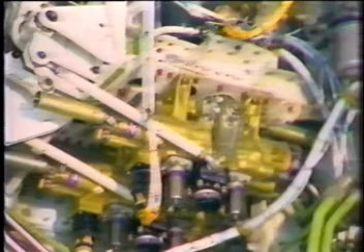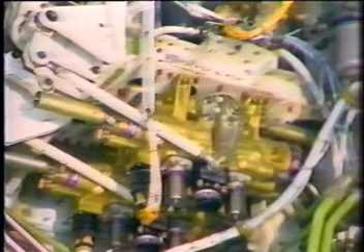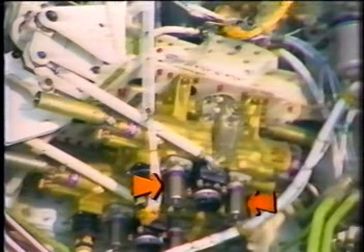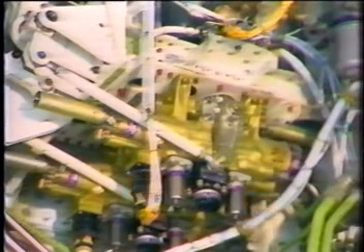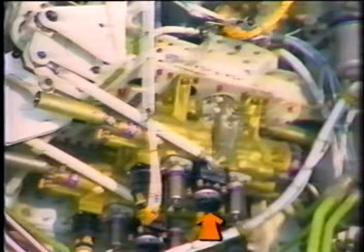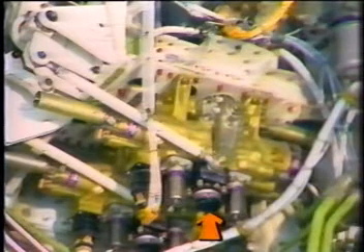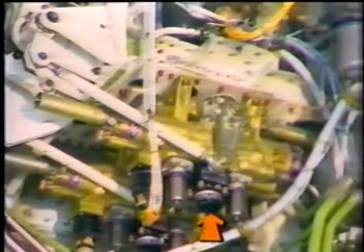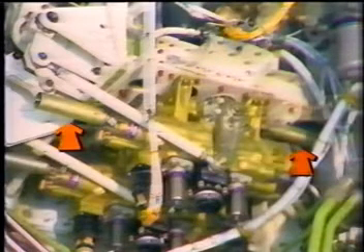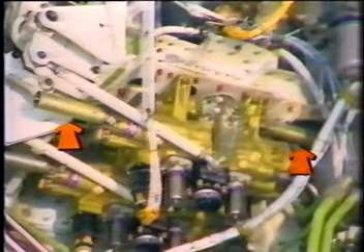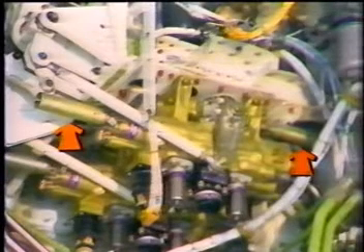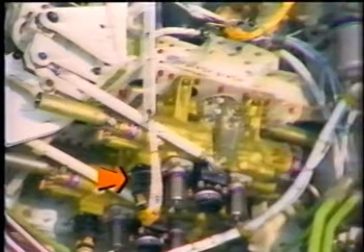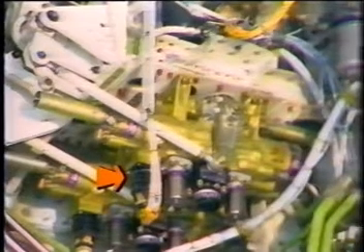Each LCA contains the following electrical components: two solenoid valves control hydraulic pressure to the internal autopilot servo to engage pistons and the electrohydraulic servo valve, or EHSV. The EHSV controls the servo piston in response to autopilot commands. Two linear variable differential transformers provide servo piston position and output position feedback to the FCC. A single electrical connector interfaces with internal servo wiring.